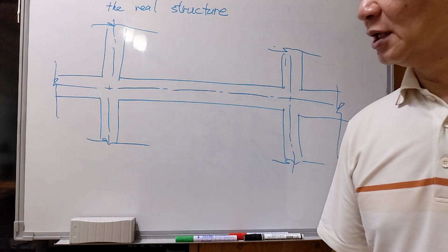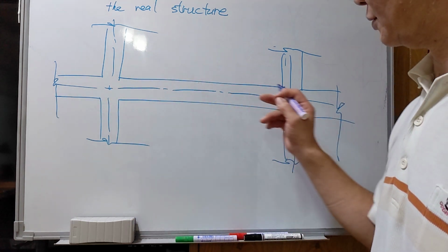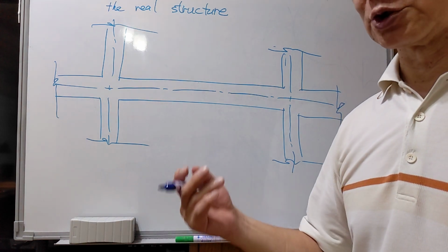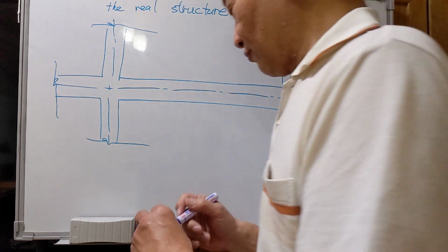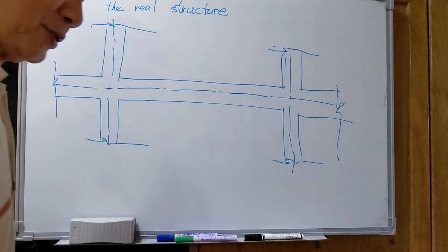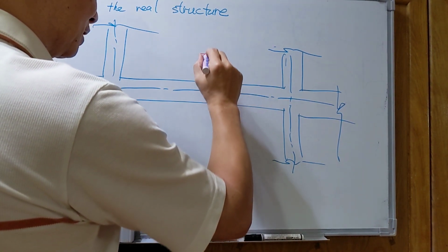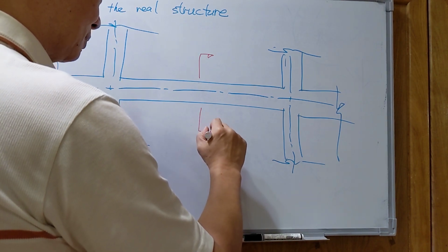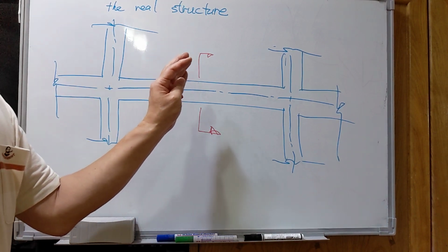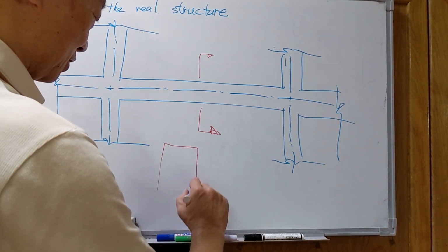In the structure model, we consider the center line to the center line. Also, we need to input the moment of inertia and the sectional area. But for most users, when they consider the elements, usually they will cut a cross section like this one. If we like to consider the beam element like this one, we will cut a cross section and check.